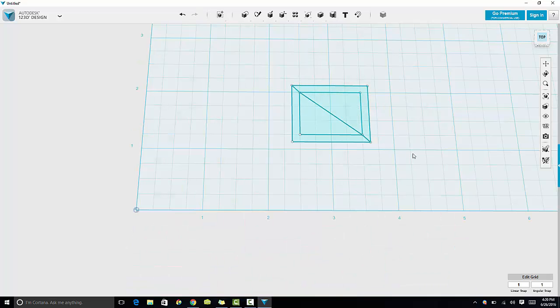So you guys can also, just another quick thing to realize, the grid will only snap to points that are an inch apart, or in this case, yeah, I think I'm in inches. So these are all inches. It'll snap to each 0.2 of an inch, I believe, 0.2, 0.4, 0.6, no, it's 0.25 of an inch.